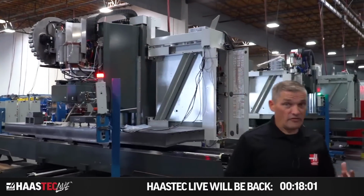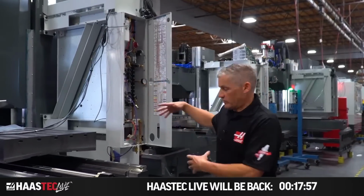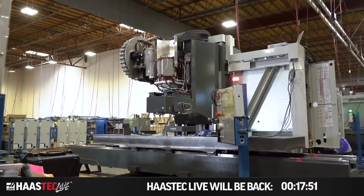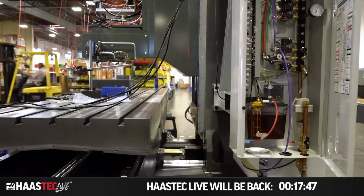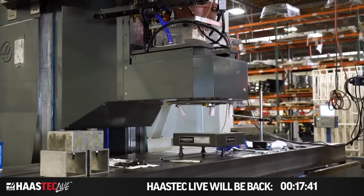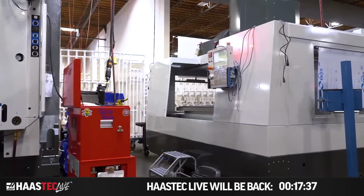So now we're in the VMC, large VMC final area. And this machine is an example of one that's in the middle of getting the geometry checked. It's kind of the same for all these different lines. You get this machine out of the casting area and you're gonna line up all the different geometry of the different axes, make sure everything is square, perpendicular. And then from there, you're gonna start installing the sheet metal, and then it goes through the whole plethora of different tests leading up to the final test cut.